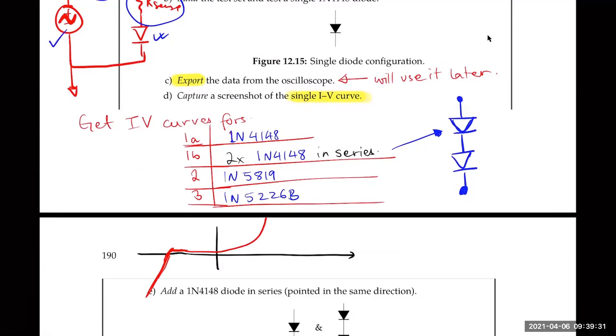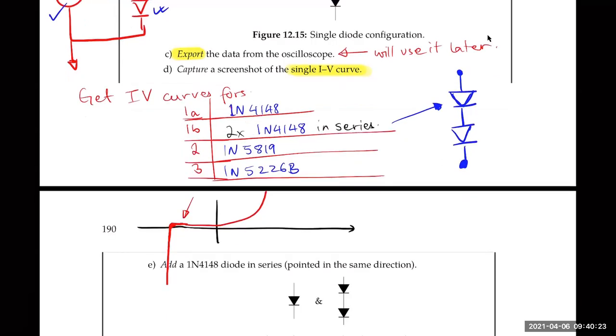Okay, so all diodes will do that, even the regular PN diodes and Schottky diodes. But what is special about the Zener diode is that this Zener breakdown is very clean and very predictable. Whereas for Schottky diodes or PN diodes, the breakdown is very noisy and doesn't allow us to make useful devices with it. With Zener diodes, the breakdown is very clean and you can make useful devices using this feature. This is one feature of the Zener diode that you will notice when measuring its IV characteristics.